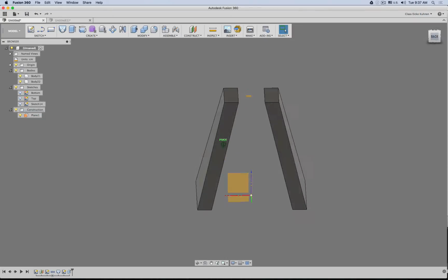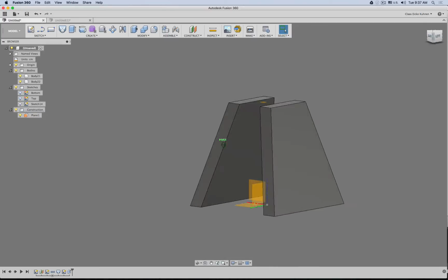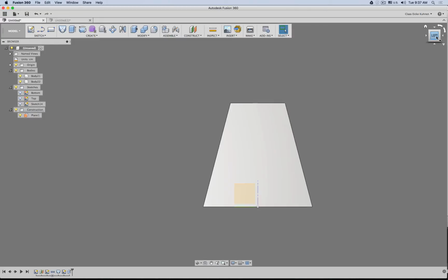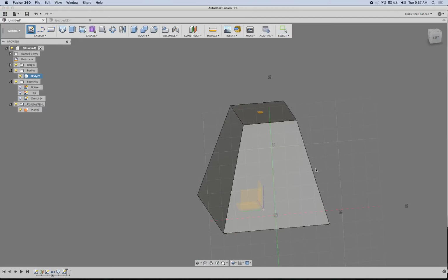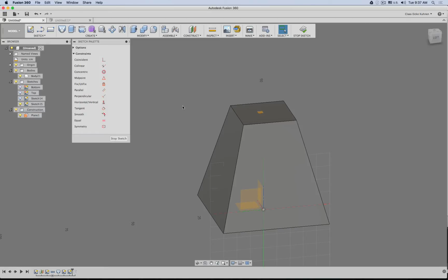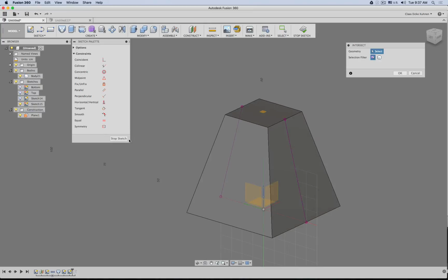The bottoms are trimmed and the inside area is trimmed. And the outside is trimmed, well, because of the pyramid we extruded first. Now I have to do exactly the same from here. So maybe back to this area, I make a new sketch on this plane. Also there I will now say intersect this face and this face.